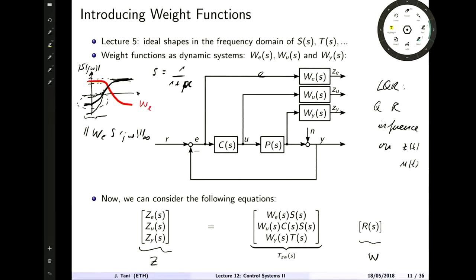Yes, it still exists. What you introduce here are upper bounds. And you will see, try it yourself in MATLAB, if you introduce bounds which are too strict, then you will not find a solution. So you don't make an equality condition on your problem, but a smaller-than condition, right? And so what the optimizer, or the H-infinity machine, tries to do is find a controller that satisfies all of this. But if you are too greedy, right, you make this sensitivity super small at small frequencies, then you will fail because there will be no solution. So, okay, good.